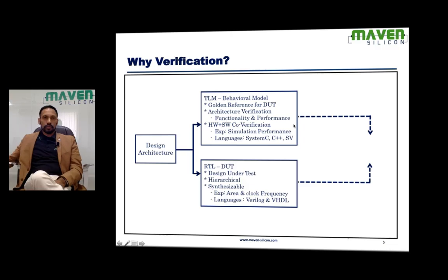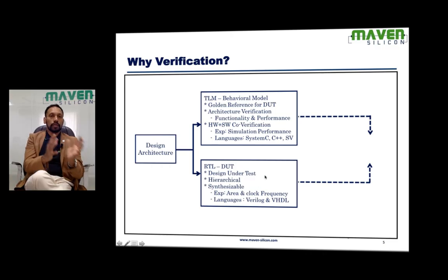When it comes to a synthesizable model, the focus will be more on area and clock frequency. This is the difference between TLM and RTL. In case of TLM, the focus will be on functionality and performance. In case of RTL, the focus will be on area and clock frequency, and eventually the model should be synthesizable. That's how we are going to generate the netlist.